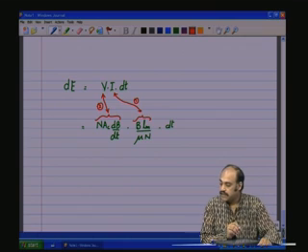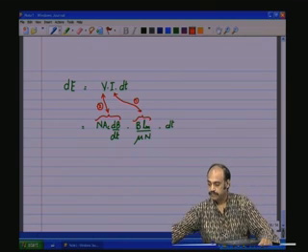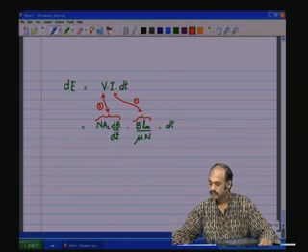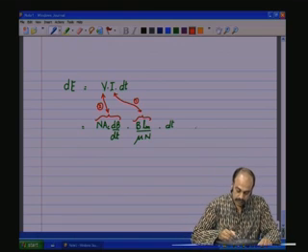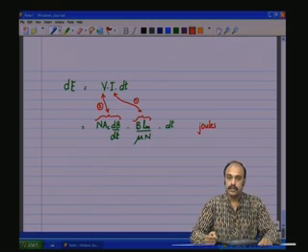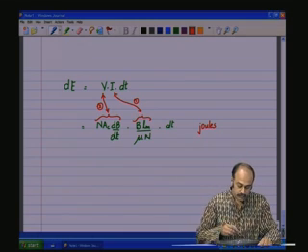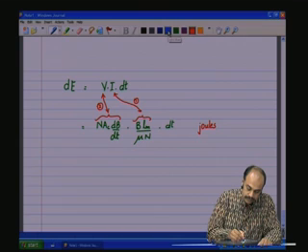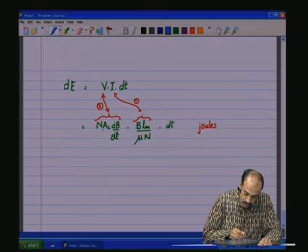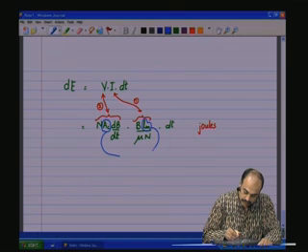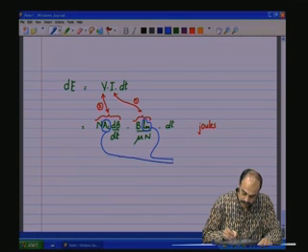This is the instantaneous energy, having units of joules, the instantaneous energy in the core. Now, here AC and Lm, the magnetic path length and the cross section area together give the core volume Vc.